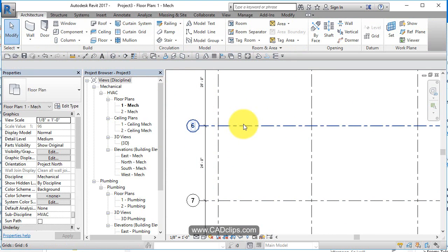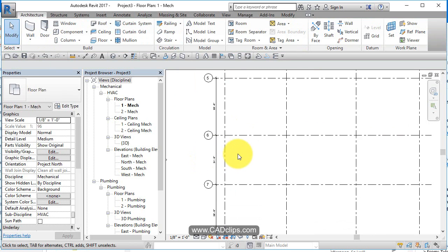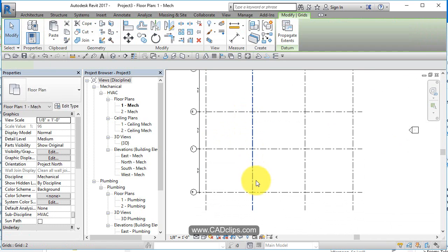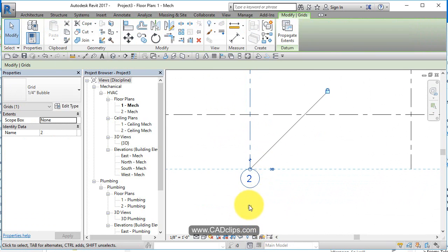Okay, the size of these are large. Remember, I changed that in my options bar to make them a 14-point font. So we've got our grid lines in there. Now, once we have our grids, you can click on here. They're kind of like levels in that you can turn the edge off or on, and you can hit the dog leg on here. Same thing with the 3D.